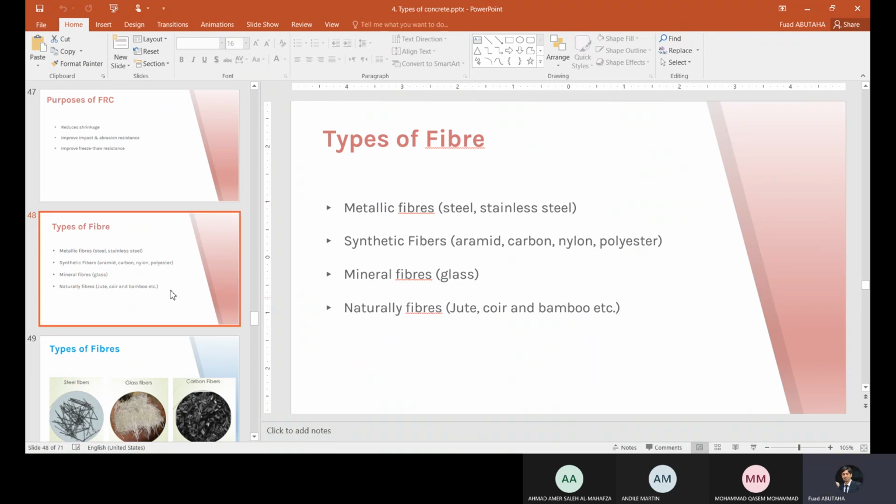And again, as we mentioned before, we have different mineral admixtures, for example fly ash, silica fume, metakaolin, rice husk ash, etc. All of them are mineral admixtures and they contribute to the strength, but the contribution is different from one type to another. The impact of using silica fume is totally different than the use of fly ash.